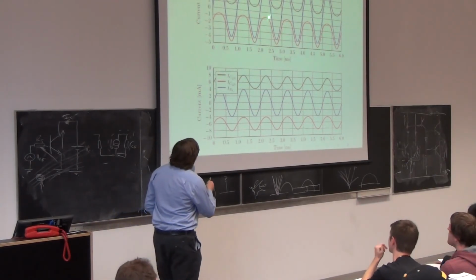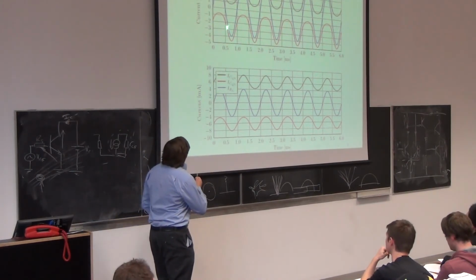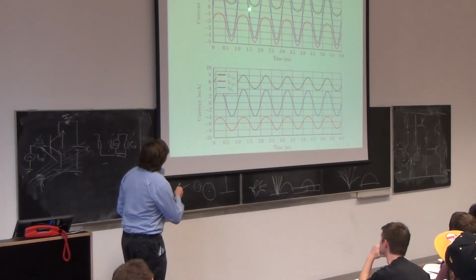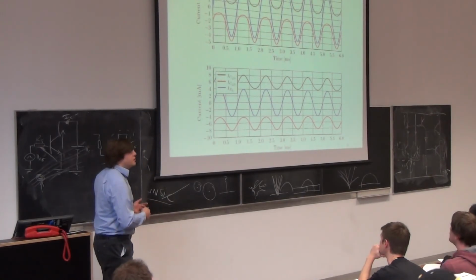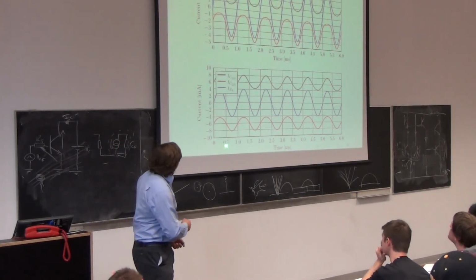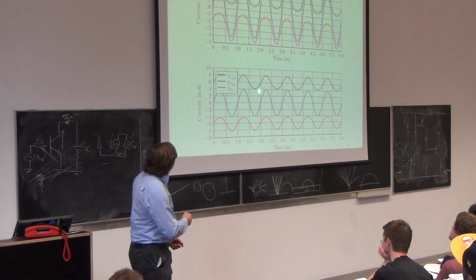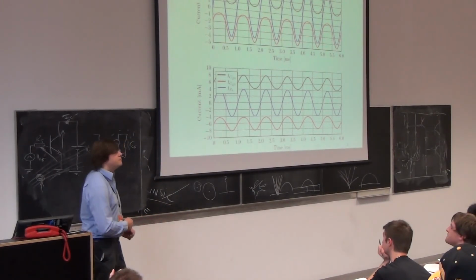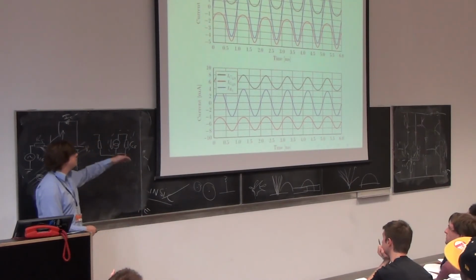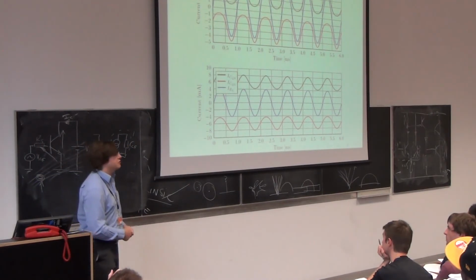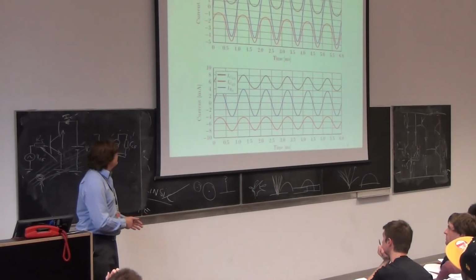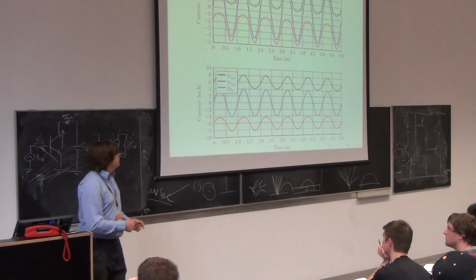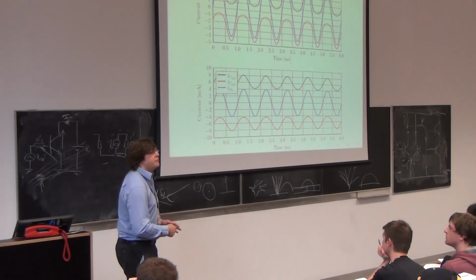So here the current waveform in each transistor is still not sinusoidal. There's still a bit where it's sort of getting towards turning off. If we keep going with the biasing, we can arrive at a situation where the load current is sinusoidal and the currents in both transistors are almost sinusoidal as well. And if I kept going more and more, everything would look like a sinusoid. So the question of angle of conduction is really just another way of saying, what's the quiescent current?